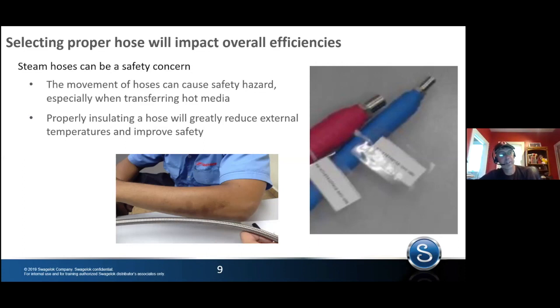This is something that's relatively common. So for this reason, hoses should always be considered for different accessories. What we show on the right is insulation to make the outside of the hose safe to touch, but there's also abrasion material that stops braid wires from abrading away, and different outside accessories that make hoses safe to touch and handle. It's always important to consider these when selecting the right hose for the application.